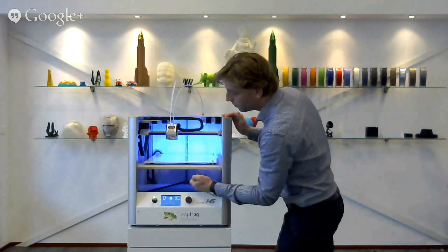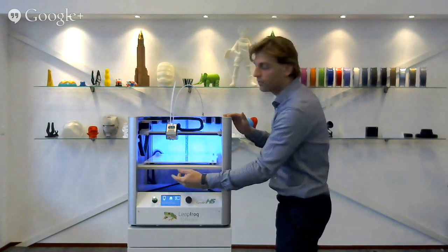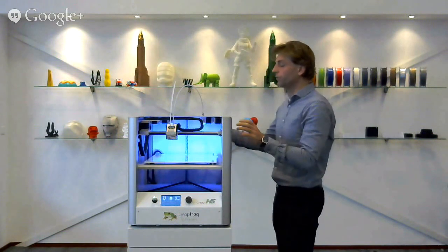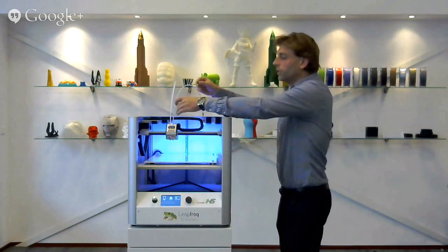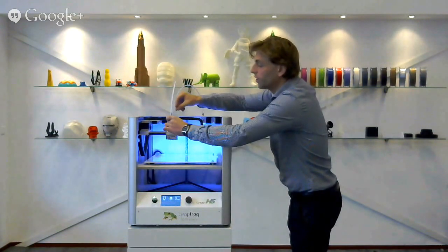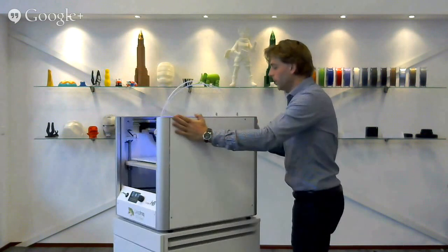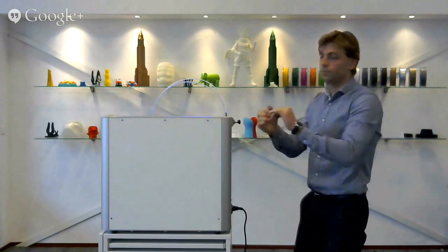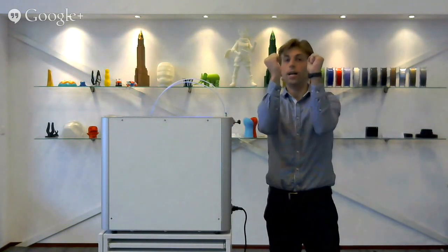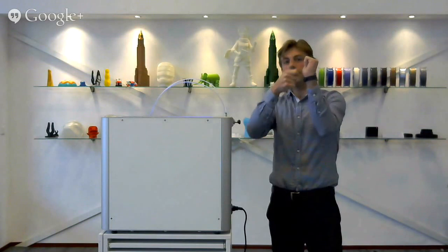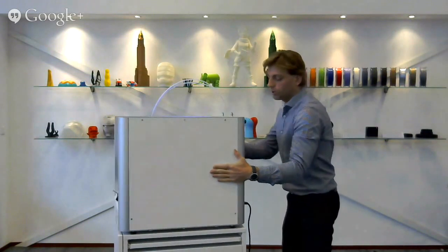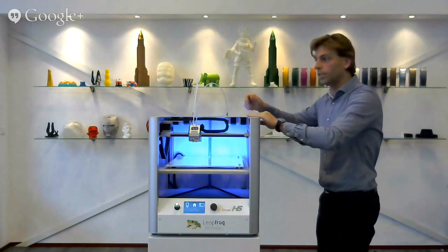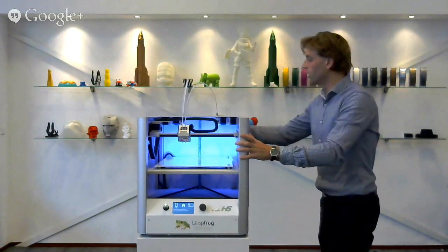We have knobs underneath the bed where you can calibrate the bed easy and fast. David will explain to you later how this works. Also, inserting the filament with the Creator 2014, you had to do it here on top of the extruder head. Now we made a patented system with this lever. You can pull on it and you can pull away the driver gear, make a gap in between, and there slide in the filament, very easy. So loading the filament is quite easy. Also, you can twist and place more tension on the driver here.